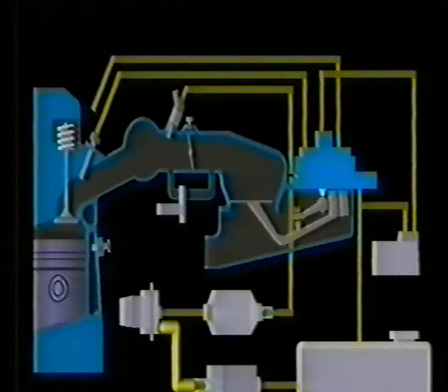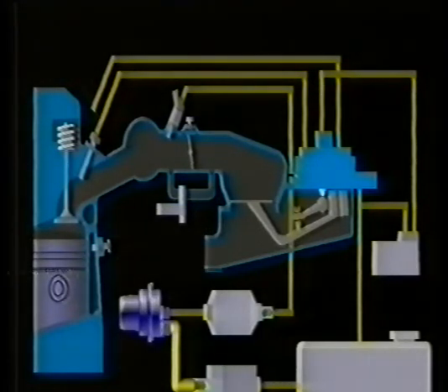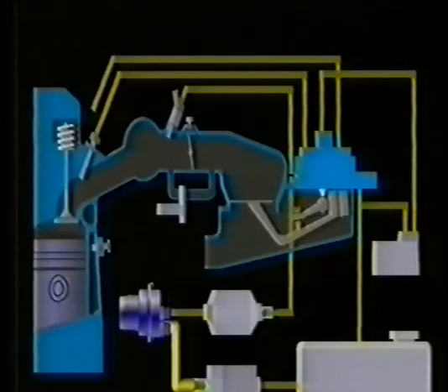The accumulator. When the engine is switched off, the accumulator maintains a residual line pressure in the system. This is known as holding pressure and is essential for hot starting capability. An additional benefit is that the formation of vapor is minimized.